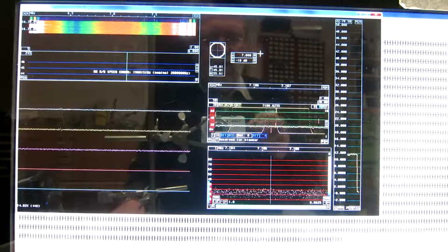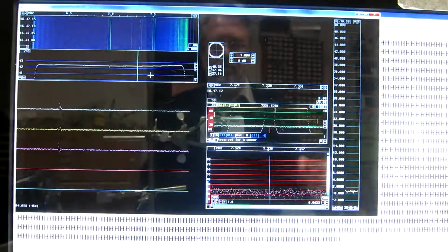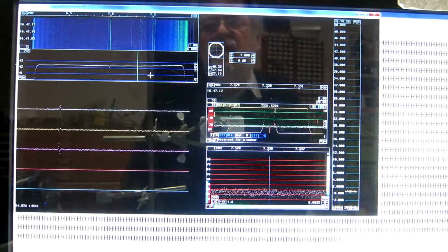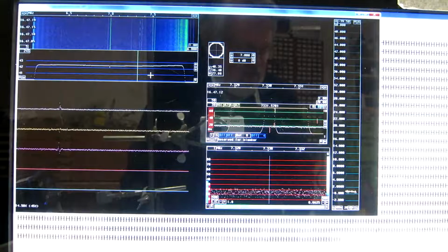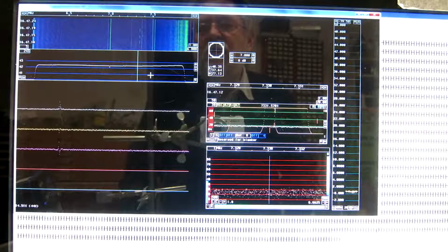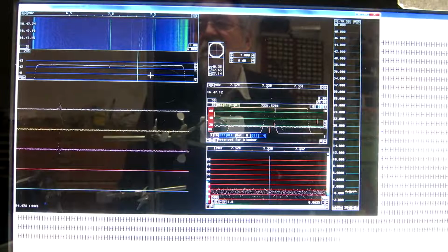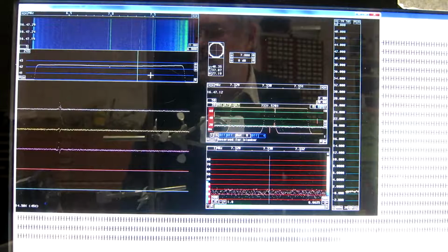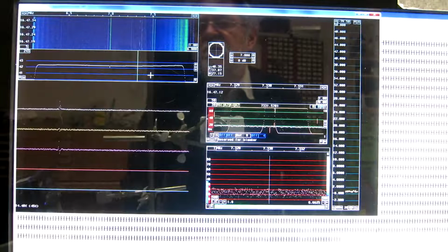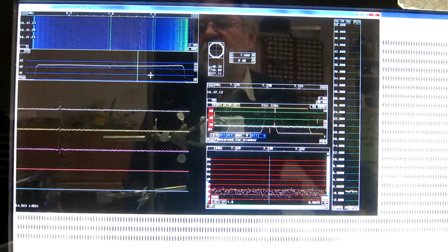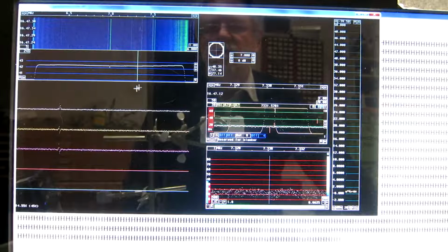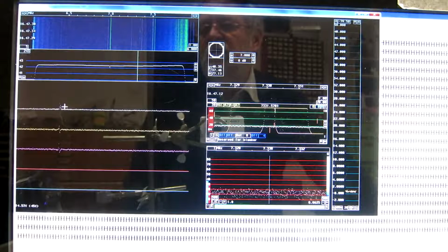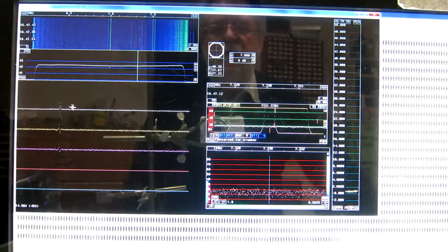Now I will connect the proper pulser. Here I have attenuated the pulses from the proper generator by 18 dB to get them to the same level as I had before when calibrating with the function generator. The pulse repetition is the same, 720 Hertz. And you can see that the remainder of the pulse is a little bit higher, but not much.